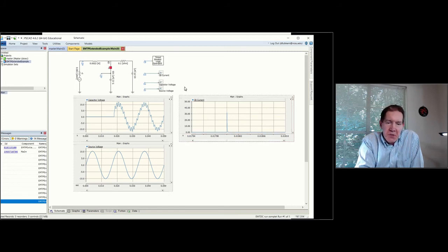And so what's sort of interesting is we've got potentially a very high stress situation right here where we basically got this current rushing through the circuit breaker as soon as the circuit breaker is closed right here. You don't see the current after that because of the scale. I mean, it's drawing current afterwards, but the current's so small it looks like it's going to be zero. So anyway, that's just one I want to point out in this case. That in real life, we got these very, very fast transients, and unless I set my plots up with really, really small time steps, I probably won't even see this right here.